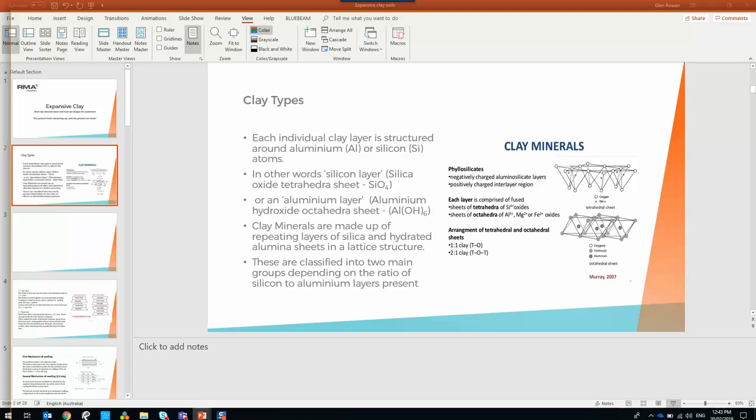Basically you just bury it under the ground, and it stays. We wrap it in plastic, so for the first week or so it's at least strong enough that it'll support the wet concrete, but then it just rots out and forms a void, hence it's called void former.